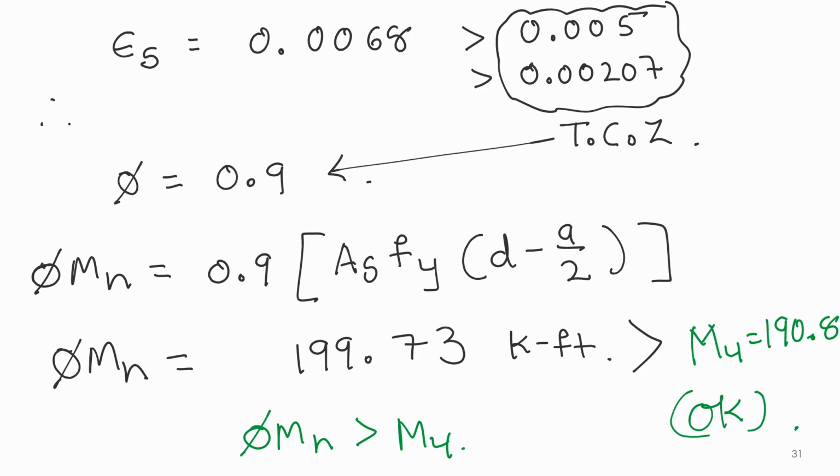When you're doing design, don't do over design. Nobody likes over design. Why? Because you're wasting money. So in our case, go something like 8% to 10%. That means that you have a good cross section. Everything above 10 to 15% will give us over design, which means we don't have a cost-effective solution. So this one is the example of how to do design of the cross section.